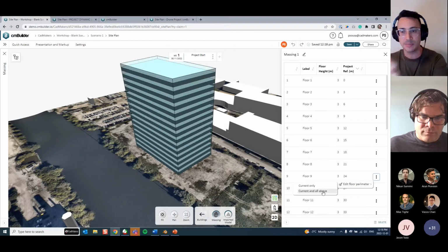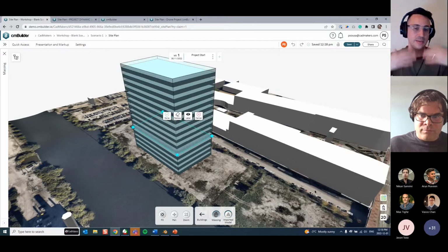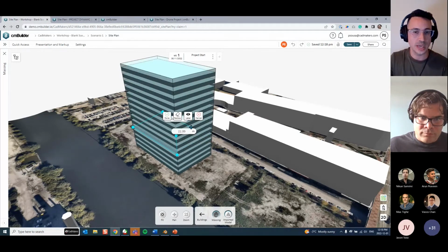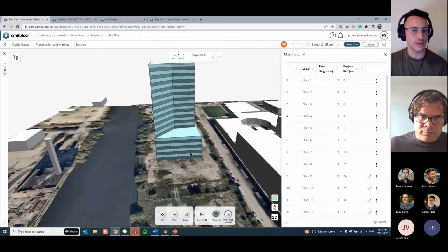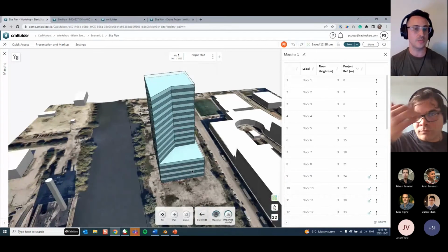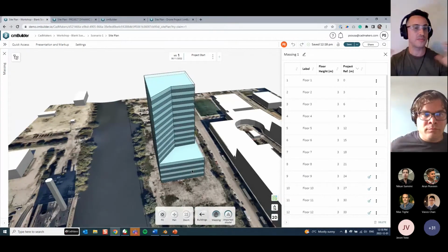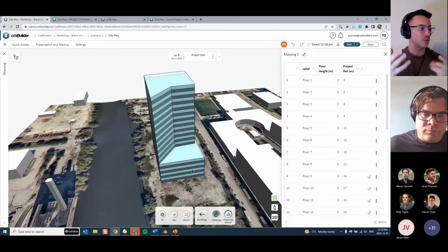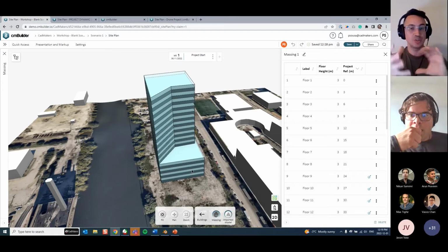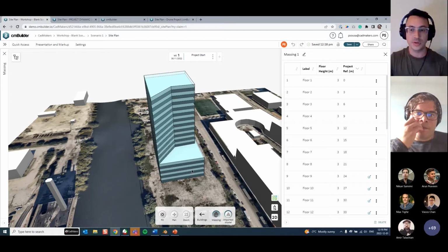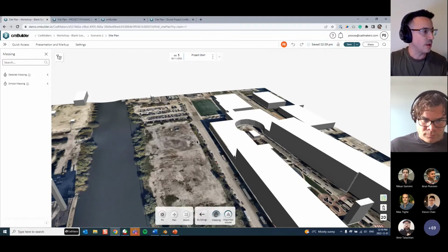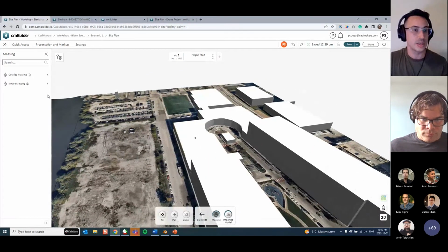You can edit the perimeter of the same floor or all the floors above, so you can do things like that. I'm not sure, Vishal, if this is your use case, but in the case where you want to represent the same building with different floor plans, this is the suggestion that we have. You simply go and start changing the shapes of the different floors. But if you do want to draw a building mass on top of another, you can do that.